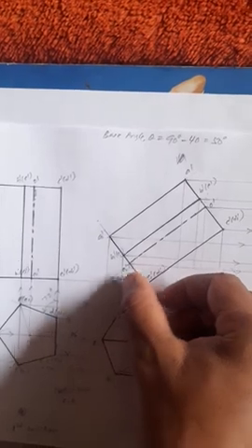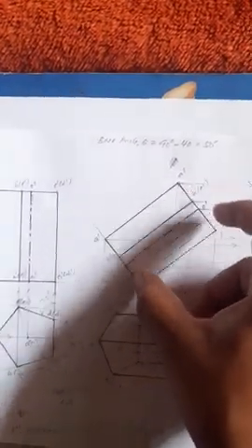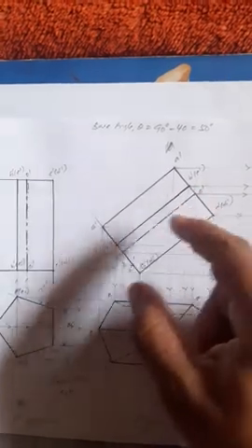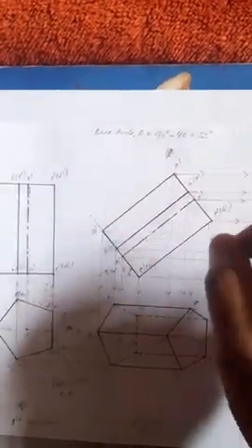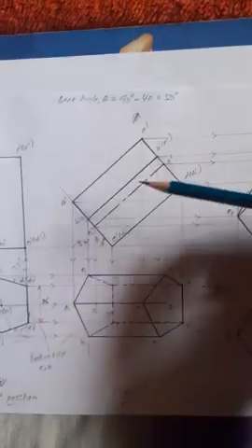40-degree, right? Once you draw 90-degree lines from each corner, measure 60 mm, then draw here and make it a visible, thick continuous line, right? Then C dash, O dash, B1 dash, A dash we will get. That completes the second position, front view.